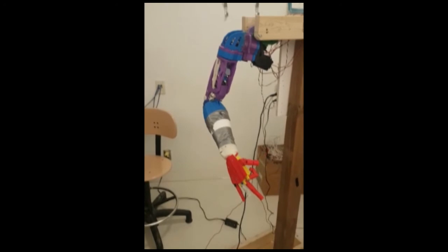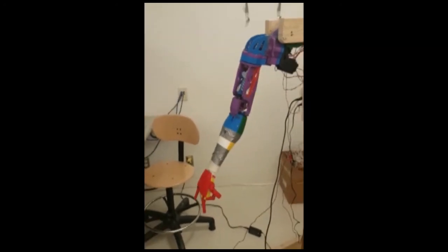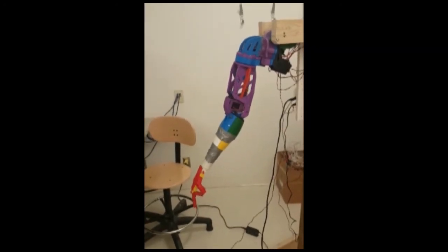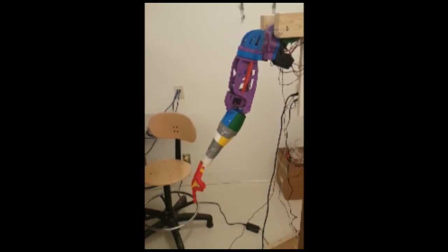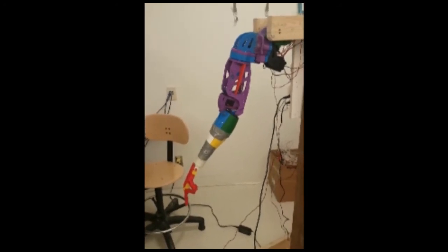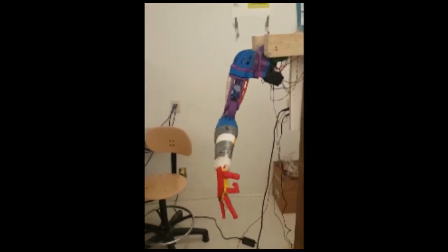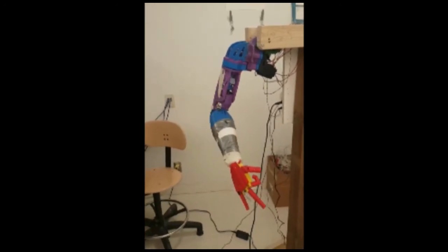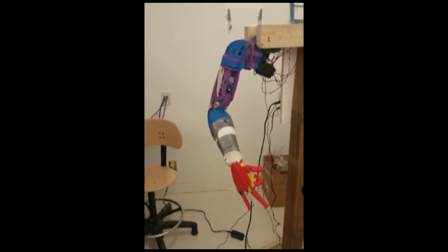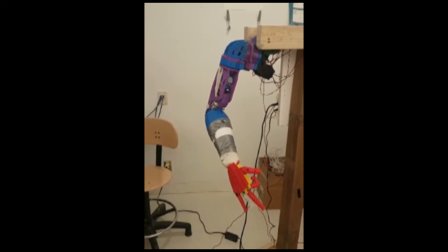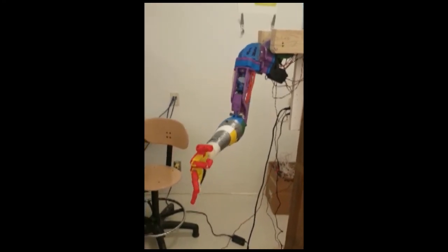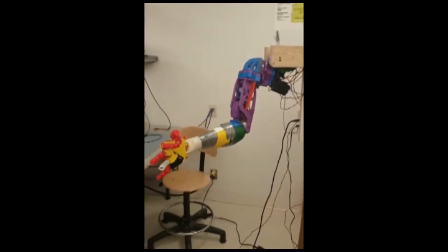As we can see from the video, a set of desired joint positions is sent to the robotic arm, from which the error relative to the actual position, read from the potentiometer as mentioned, is computed and to which the PID loop is applied. The result of this is that the robotic arm reaches its commanded positions accurately and without any significant delay.